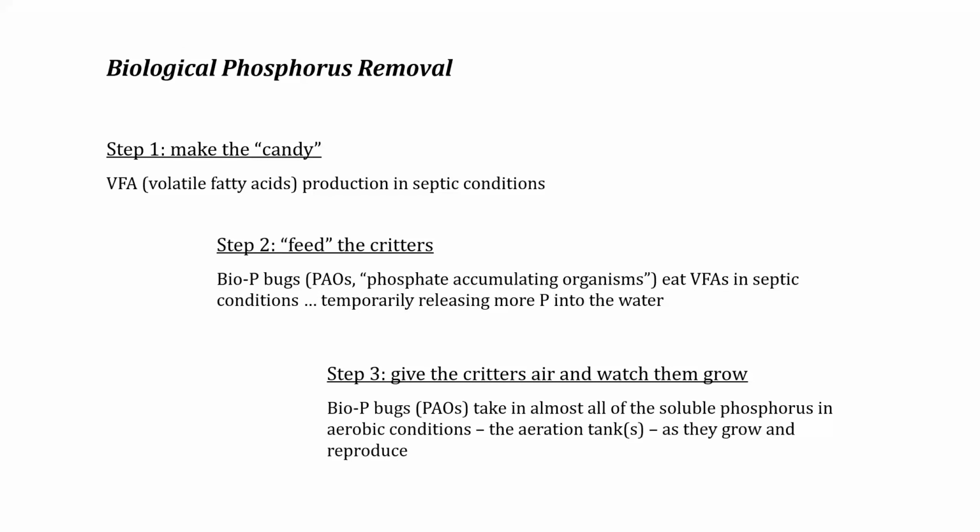So in the aeration basin with a pH of 6.8 or higher, enough oxygen to remove ammonia, you should have a good environment as long as there's a little bit of BOD still coming into that aeration basin to support biological growth. And I want to come back to that point, so I'm going to make a note on that.